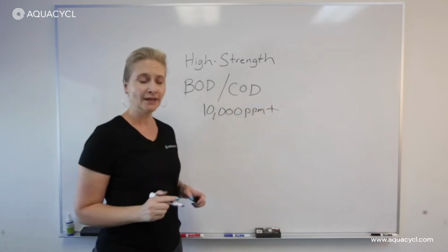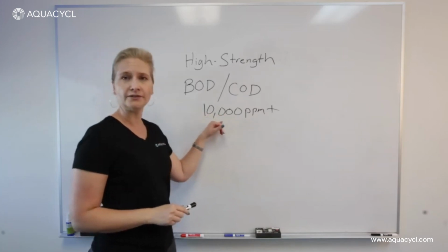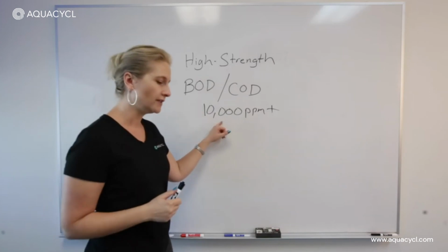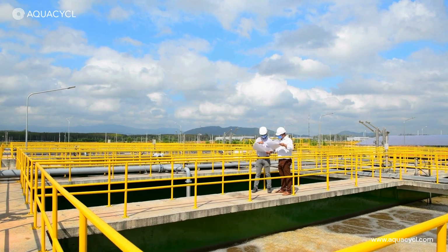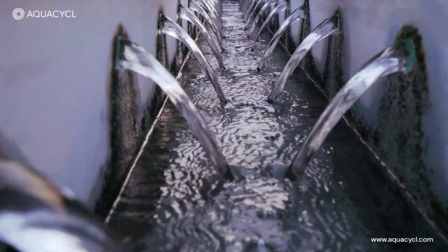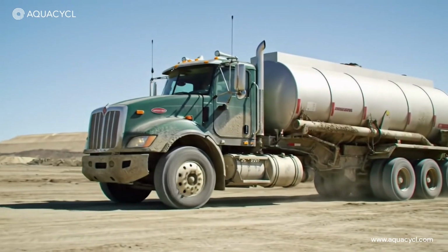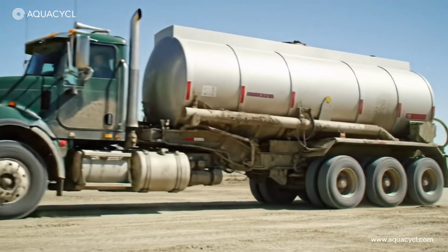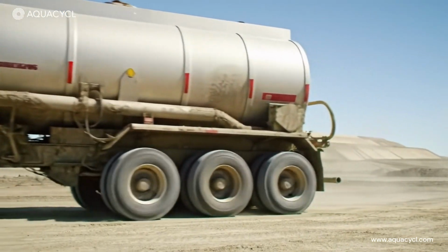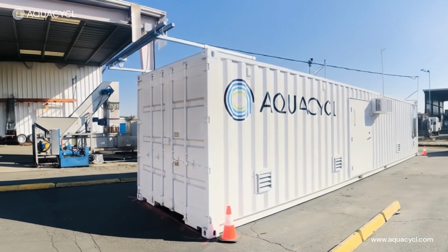and higher. So when you're operating and discharging in concentrations like this, you have to take into consideration, okay, where am I operating? Can the city let it go down the drain? If that answer is no, you're going to have to haul it somewhere. So you have to pay a hauling company so it can dispose of it, either taking it to a different municipality that can treat it or maybe land apply it somewhere. Your other option is to do industrial pretreatment on site.